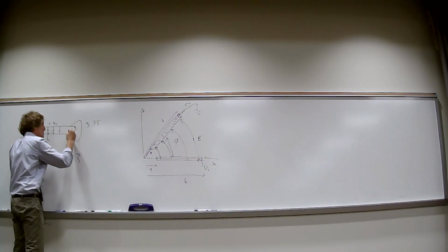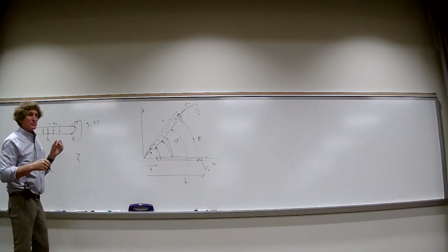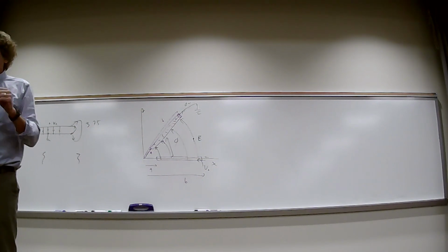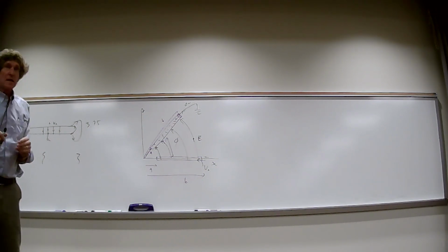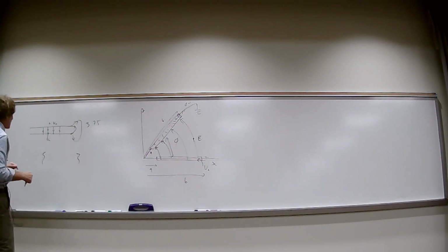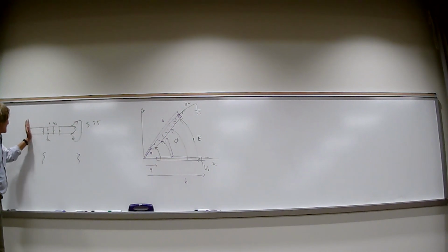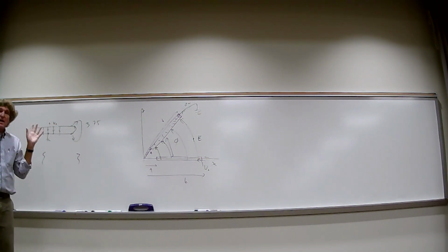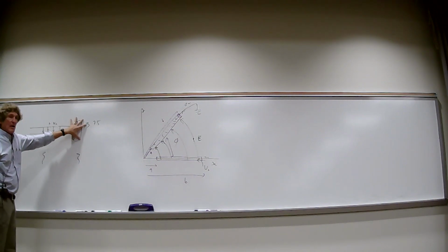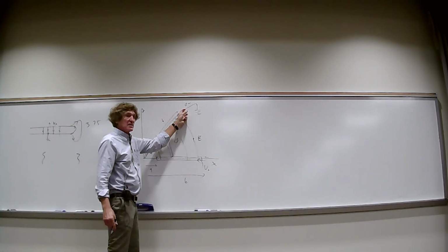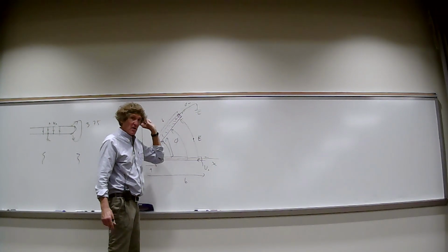Now the electric field, when it maps on that side, if you solve the actual equations, is not going to be just straight down. Y'all follow me? That's called field fringing. Normally, we neglect that in most capacitive problems, and here's why. About 99.99% of the electrostatic energy that we'll get to today, hopefully, is between the plates. There is a very small amount of fringing fields, but usually it's insignificant, okay? So when he says neglect the fringing fields, he's talking about neglecting the fields that are not in the phi direction. Do y'all follow me?